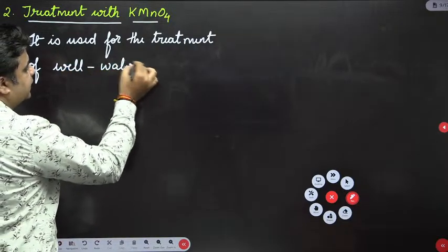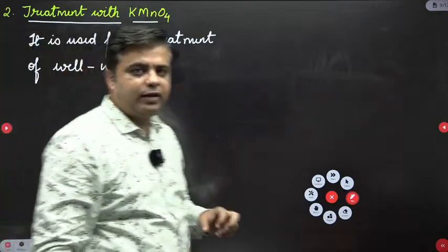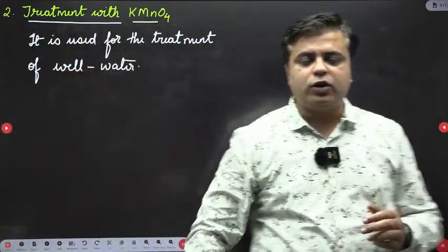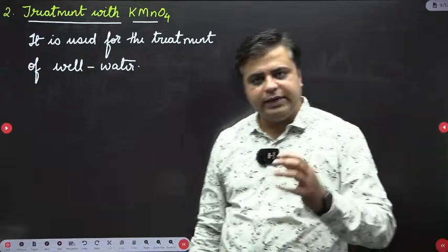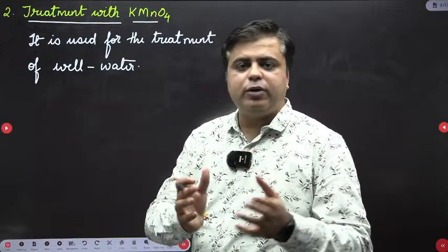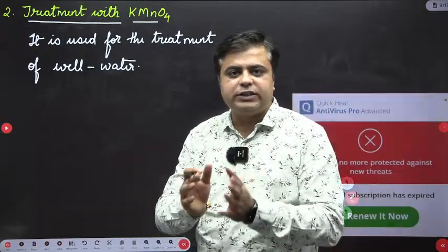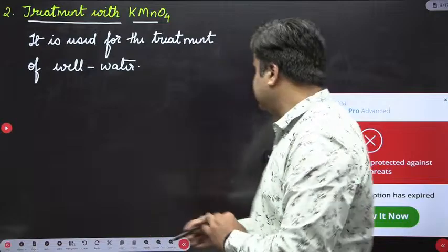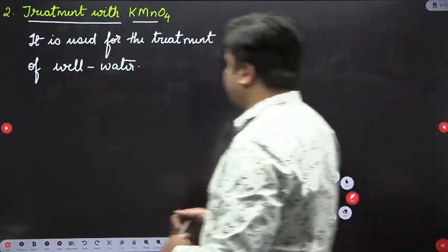So what we do basically, we add KMnO4 in the well, and we don't utilize this water for the next 48 hours. We leave this water for 48 hours, and in 48 hours, this KMnO4 will carry out the disinfection of all the pathogens which are present in the water.